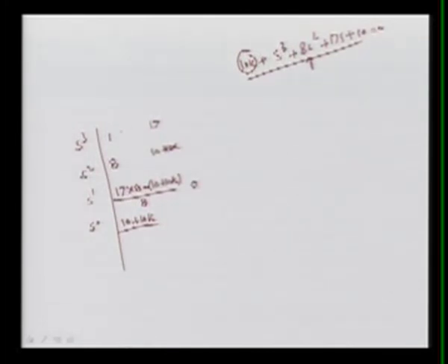So what we have to see for the Routh criteria is that the first column should be positive, and let us see when the sign is going to change. Here, the first criterion is that 10 plus 10k should be greater than 0, all positive, it must be positive. So we are getting k should be greater than minus 1, and that is always true.